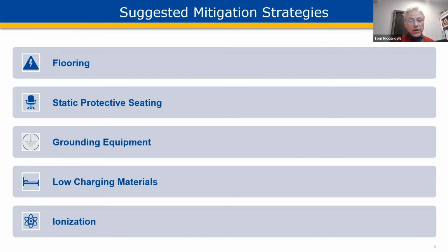Where they can be very effective in a healthcare setting is at the entrance to, say, a surgical suite. People will be coming into that suite. They may be carrying a charge on them, and as they go through the entry, that charge can be neutralized effectively with an ionizer. If you recall the last presentation, one of the risks we want to discuss is static charge buildup can cause particles to attract to a body. So things like germs can be adhered to your clothing, your gowns, whatever it is you're wearing. An ionizer can help reduce that. Basically, as you walk past an ionizer, if it's designed and implemented effectively, it can cause those particles to neutralize and actually fall off. And there have been some studies to show that. So it can be a very effective tool.